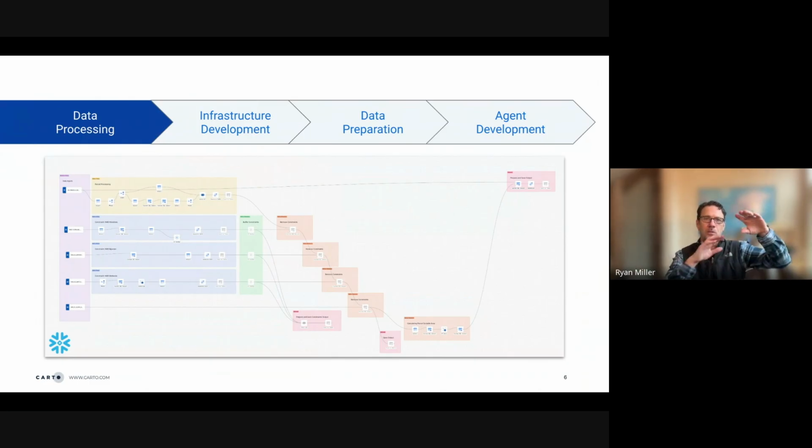So we've got our parcels, we're subtracting out those stream buffers, the areas that exceed certain slopes, etc., and saving an end result data set that has these constraints removed. That would be our buildable areas in this particular example.